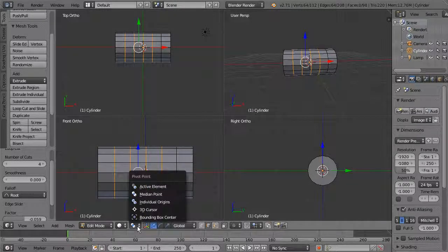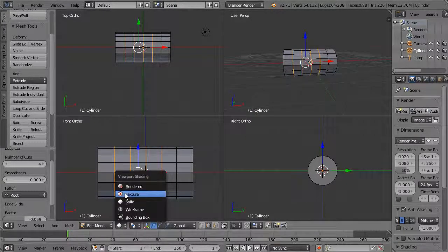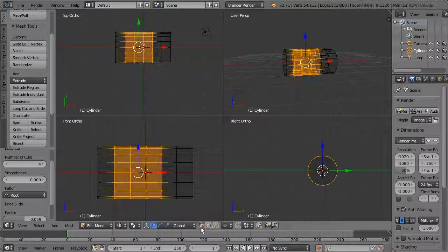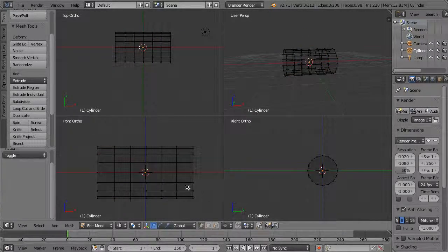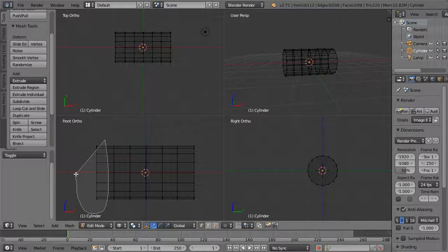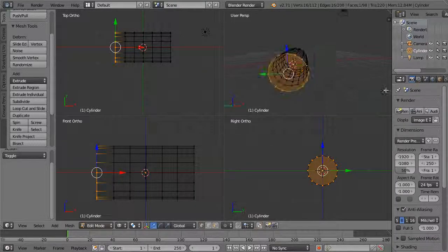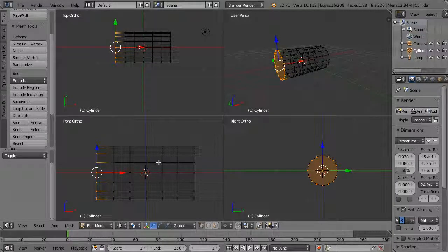And I want to turn on Wireframe. Okay, so I can display it as a wire, and I want to select the points. I'll hit A to deselect, and now I want to be able to select all the way around, like a lasso select. So let me zoom in here. I'm going to use Control left mouse button with Wireframe on, and you can see that selects the entire loop there. So at this point, let's do some shaping on this.